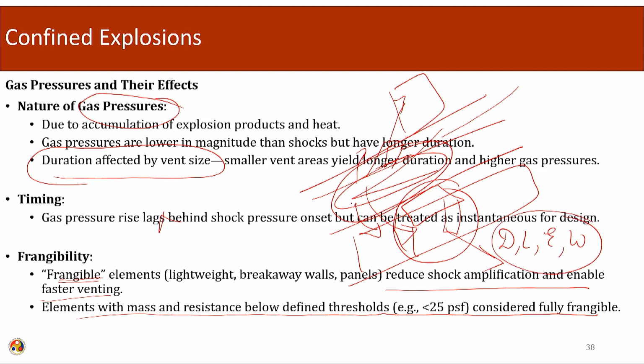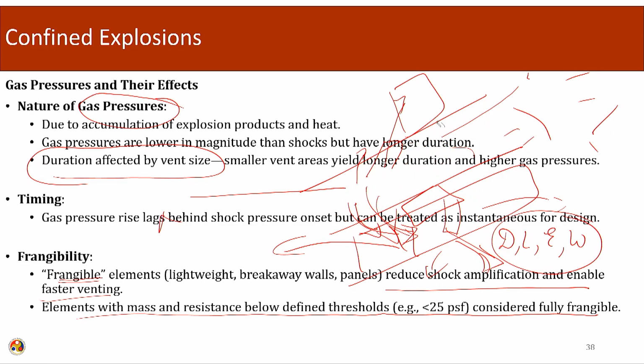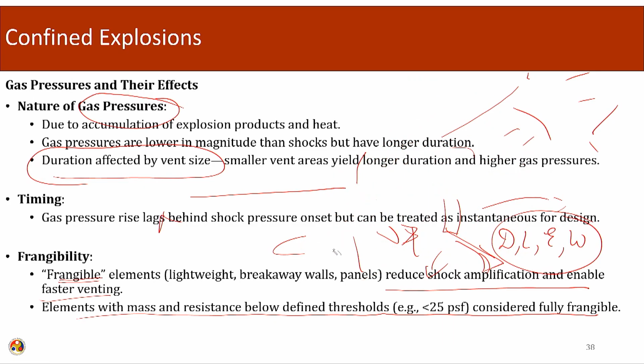But if it is hit by an aircraft, it will dismantle, it will break away instantly. So a normal threshold load is there, as per the aircraft guidelines. If this structure sees an impact load, the whole thing will be dismantled, everything will fall apart. So this is one more application of the frangible element. Same concept is used here also.